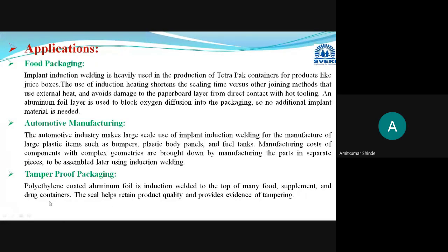What we are doing there is using polythene coated aluminum foil. In that, we are doing induction welding. Due to that induction welding, the particular food or drugs or medicine can be protected with the help of this tamper proof packaging. So these are some applications of high frequency induction welding and implant induction welding.